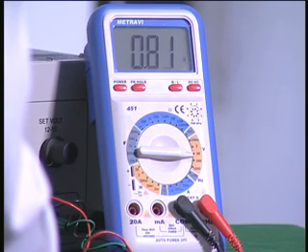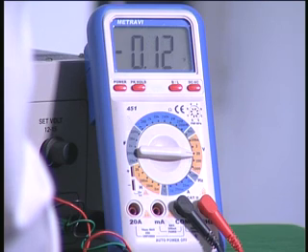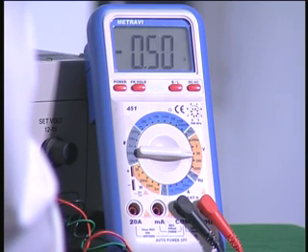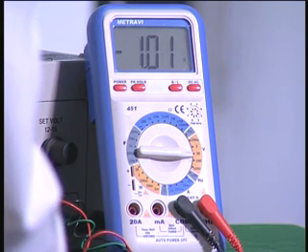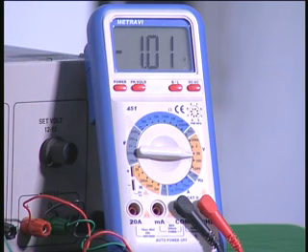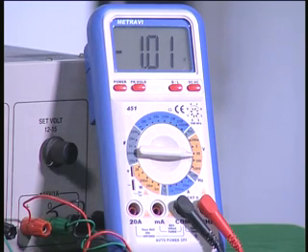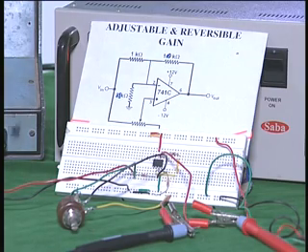As I change the potentiometer, the output voltage keeps decreasing: 0.7, 0.6, 0.5, it keeps on decreasing still, and it comes to nearly 0, and then you can see that it has come to minus 2, minus 3, minus 4. I keep moving in the same direction on the potentiometer, minus 8, and finally when I come to the complete end, it becomes minus 1.01. Minus 1.01 divided by the input voltage, which is 0.1, gives me the gain, and therefore the gain is minus 10. So all that I have done is vary the potentiometer from the minimum value to a maximum value, and the gain goes from minus 10 to plus 10 as I vary this.